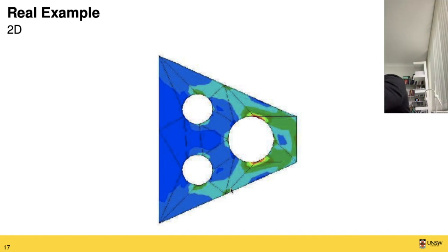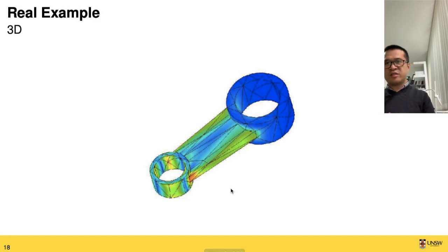You can move on to more complex materials such as this three-dimensional component in machinery, where you probably use some triangle elements to simulate the rounded part, and more elongated triangles for parts that have a more regular shape. You can subdivide these elements into finer and finer elements, so you have more detailed modeling of how the stress will be distributed in this irregular shape.